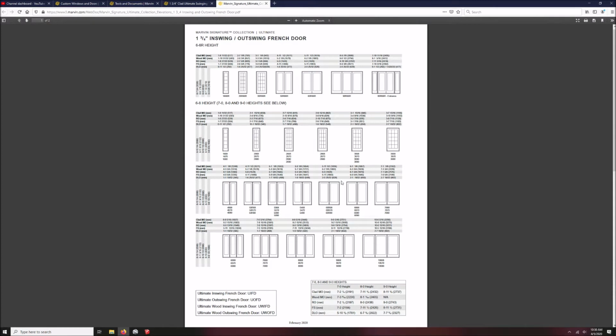And as far as the height, we'll look at the little table in the bottom right. An 8 foot high door has a frame size of 7 feet 11.5 inches. Same thing, it allows a 1/2 inch gap at the top of the door. So we're actually going to make our door with its frame to be 5'11" wide, 7 foot 11.5 high.